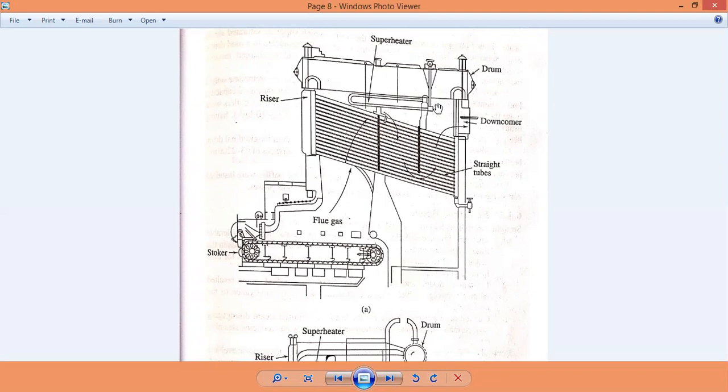The density difference is called natural circulation. As the heaters are running at different temperatures, the water and steam mixture is at a different pressure inside, and thus there is a density difference. It causes higher densities to move down and lower densities to move up.